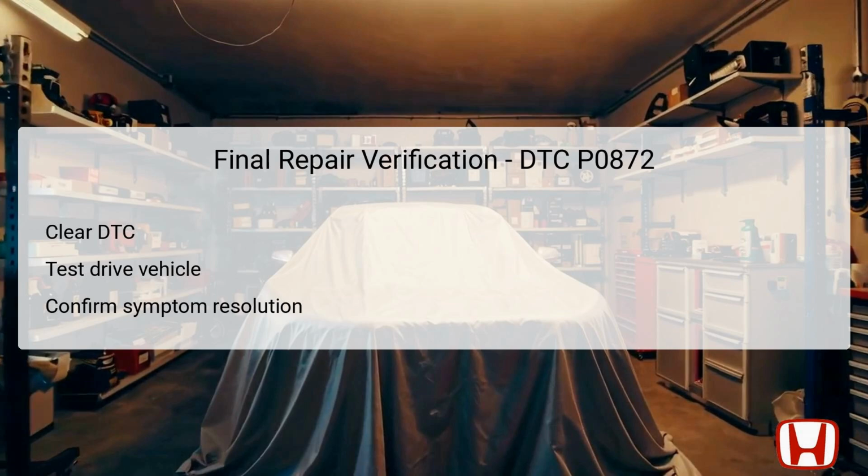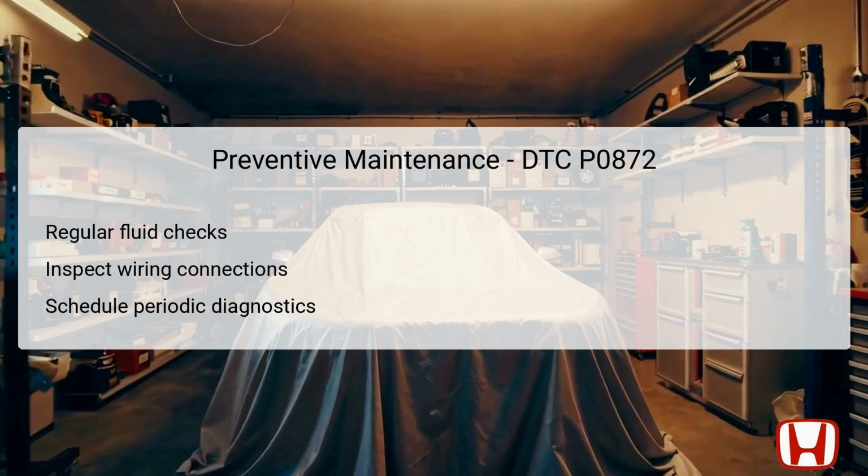Preventive maintenance is crucial for avoiding recurrences of DTC P0872 and ensuring optimal transmission performance. Regularly checking transmission fluid levels and condition should be a routine part of vehicle care. Low or contaminated fluid can lead to switch and transmission complications.